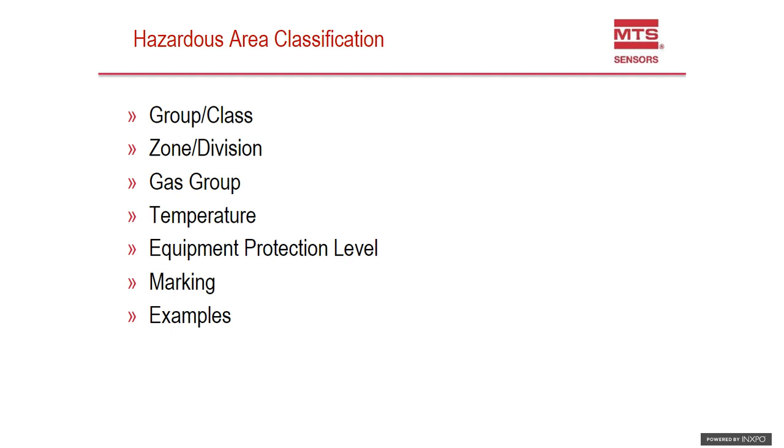The ratings are all trying to describe the different groupings of explosive liquids and gases and how much energy is stored, because that determines either for explosion proof, how strong your housing or your containment must be, or for intrinsically safe, how small of an amount of energy you can have inside the device. So there are very large differences depending on which letters are chosen.